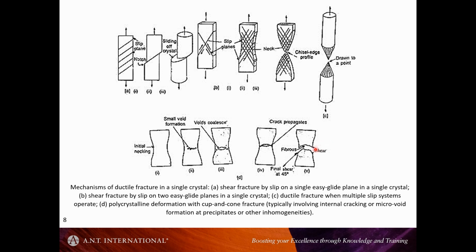And a typical thing that happens in many thick specimens is that at the edges you get into a condition of plane stress, and what I mean by that is the stress component perpendicular to the surface of the specimen is zero, so there's only stress within the plane of the material.